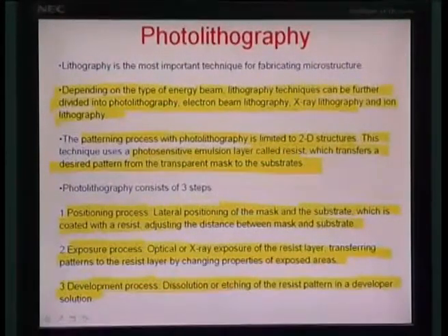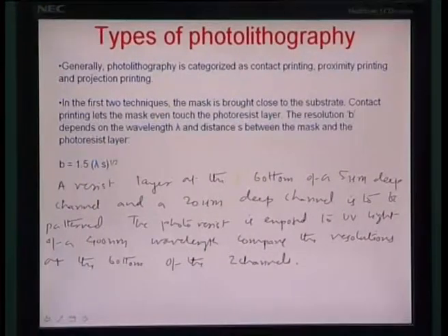Okay, and let us also look at what is the difference between the contact, proximity and projection lithography. So, essentially it is the distance at which the mask is placed from the substrate. In contact and proximity, they are very close by. Projection, where it is at a high distance for reasons mentioned earlier.